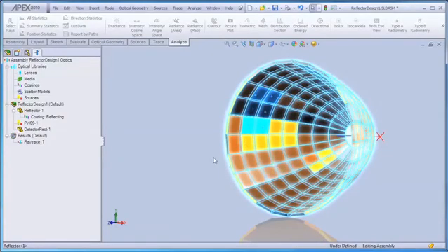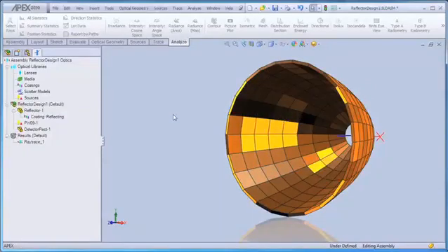And we can assign properties only to those surfaces that we've chosen while ignoring the rest of our system geometry for ray tracing purposes. So we can see that creating optical system geometry and assigning optical system properties is a simple point and click process within the Apex environment. Now that we've created our optical system, we're ready to create and insert a source, and this is the next step in our Apex workflow.